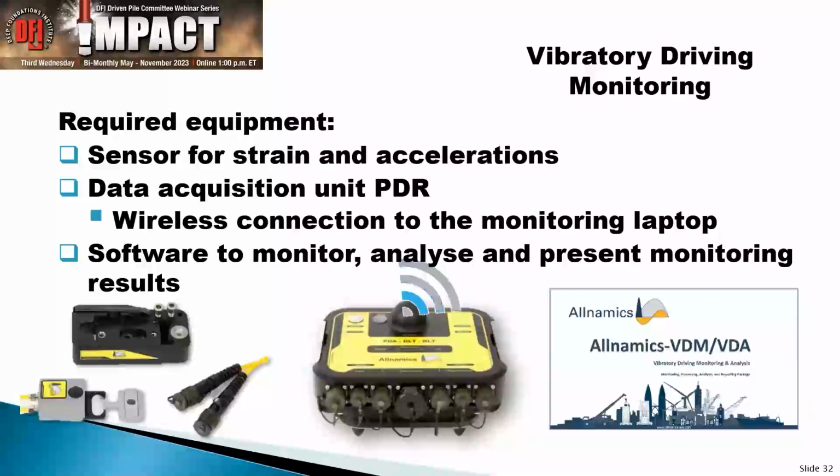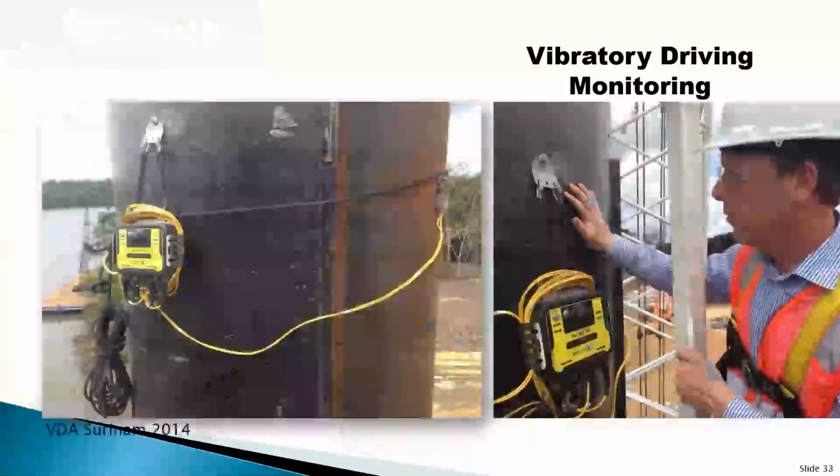You need to send the data. Most of the time we put something on the pile that has a wireless connection to a laptop where you get all your data. And then we need to analyze the data, just what you would do with PDA, and we call it in VDA, a vibratory driving analysis. But it's pile driving analysis. Exactly the same thing that you normally do.